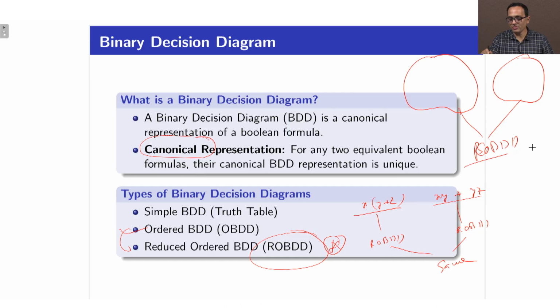Right. So this is the advantage of ROBDD, which is a canonical representation. It has very wide use in circuit optimization, formal verification, model checking, SAT solvers, everywhere. This is a very important data structure and we must learn it in a formal methods course. Although I have introduced what a BDD is, logically a DAG, finally we will see how we can get the ROBDD. With an example I will show you.